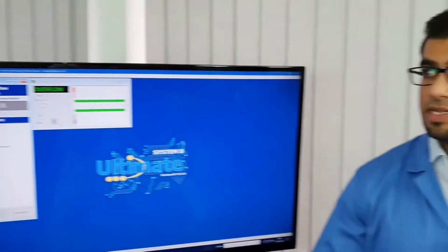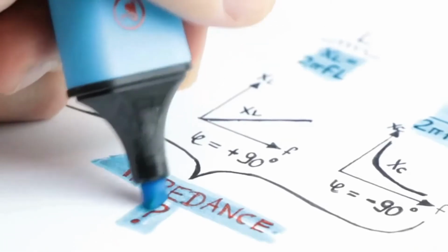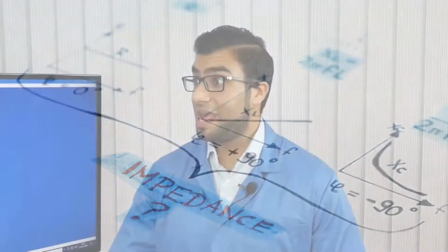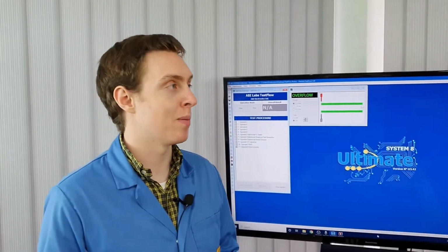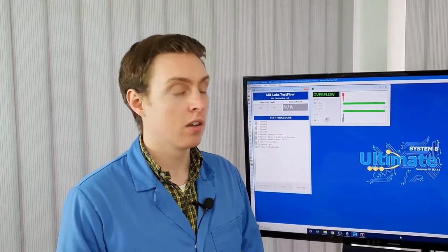Okay, so you may find if you test an old board compared to a newer one, that the impedance increases, and that's an indication that that PCB or that specific component may need replacing now, or maybe sometime in the future. Okay, so you don't even need for that part to break down. You can see that it might break down next year, and that's something you can regularly do. Simple with a short locator, just seeing the impedance increase.